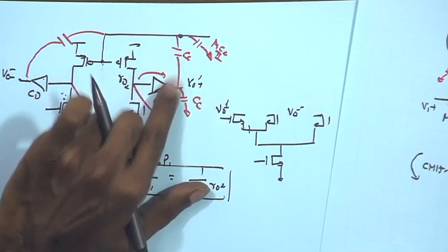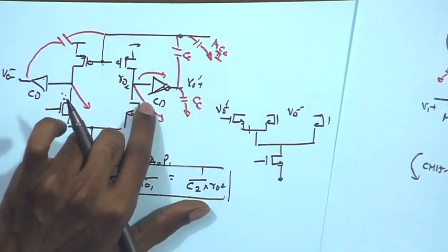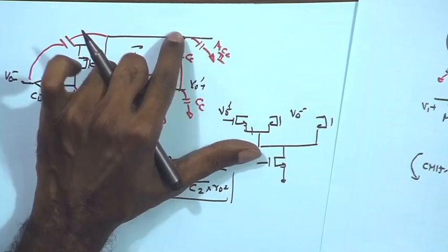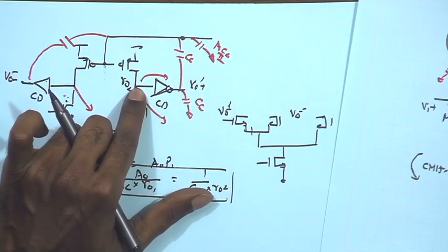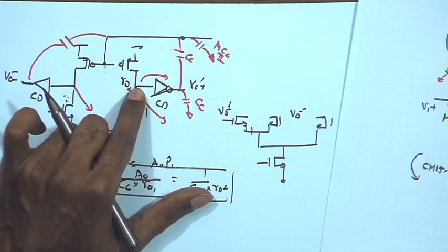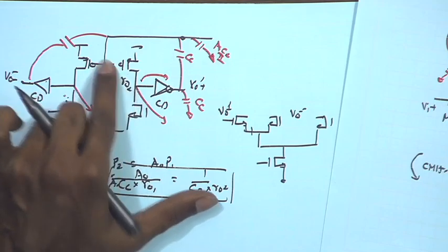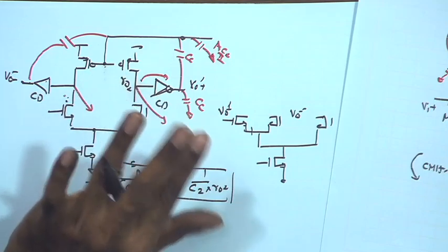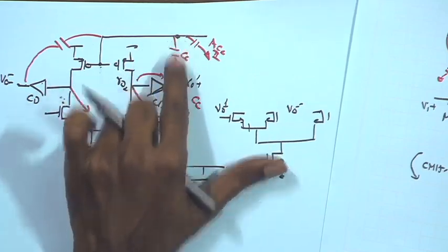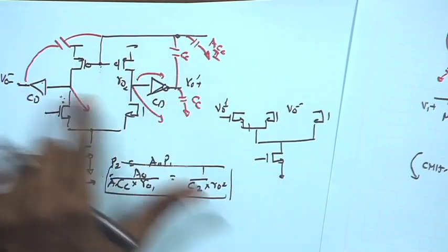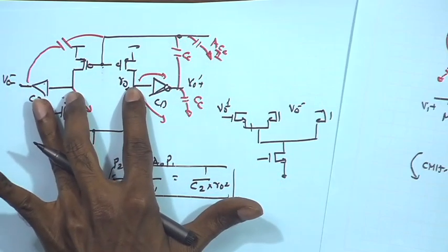If you decouple that using a buffer, then that factor will not come into the picture. However, if you have the capacitance connected between this common gate point and the output, then of course that will come into effect. But that will also degrade your differential gain and can create problems with your differential operation also. Therefore, it will be better to decouple the differential operation from the common mode feedback. So, if you are trying to stabilize the common mode feedback, it will be better to avoid its interaction or interference with the differential operation.